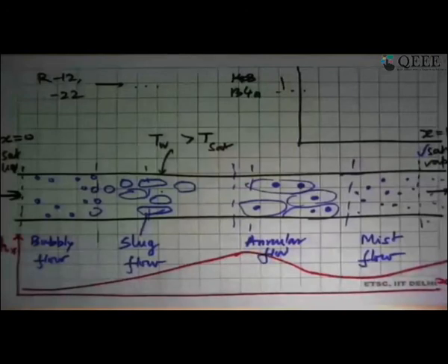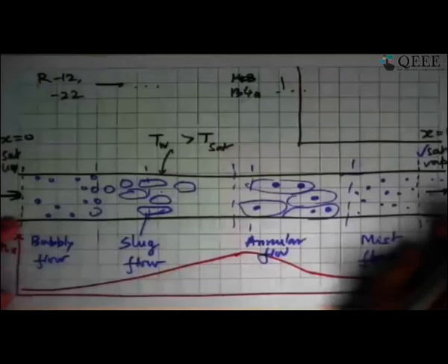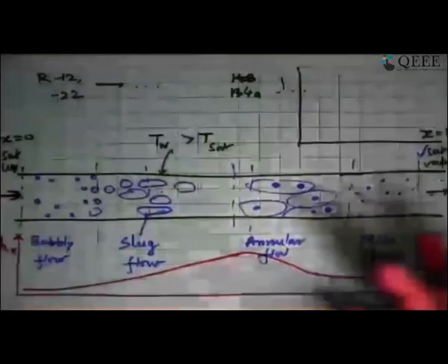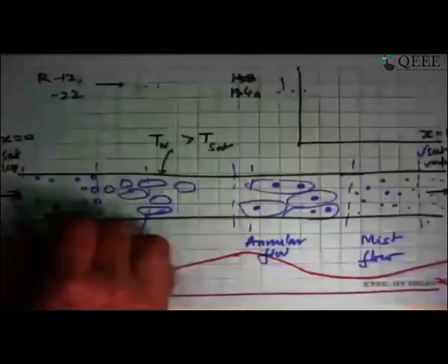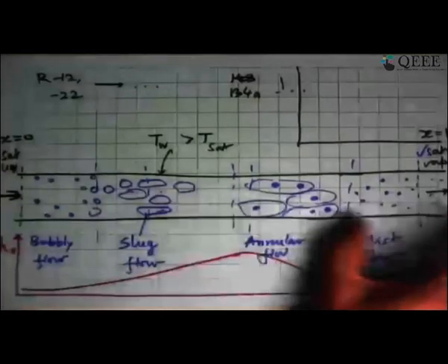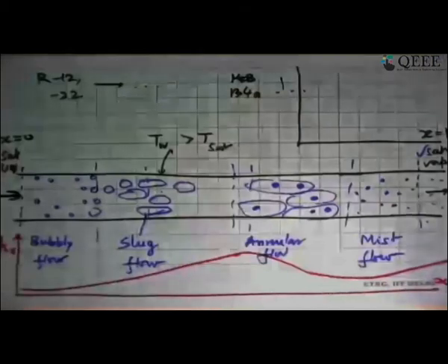So we have hugely varying heat transfer coefficients along the length of the tube, and so what length of the tube to actually put is not just determined by the average heat transfer coefficient, but by approximately the portions over which each of these regimes takes place.